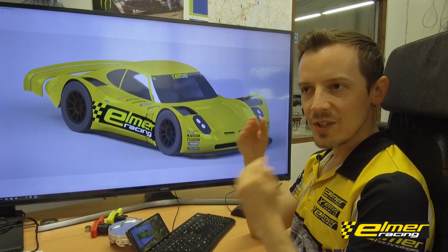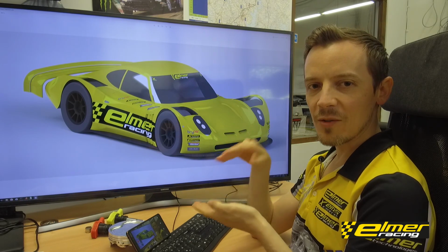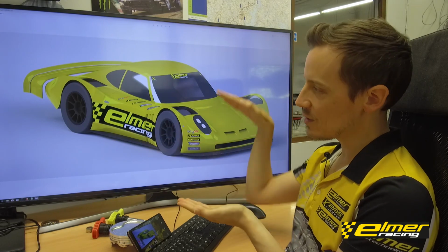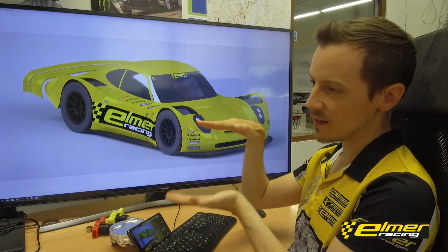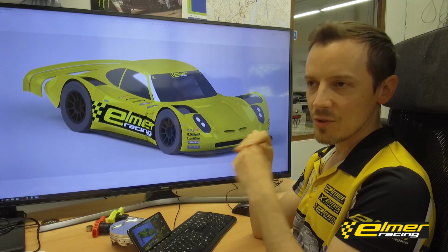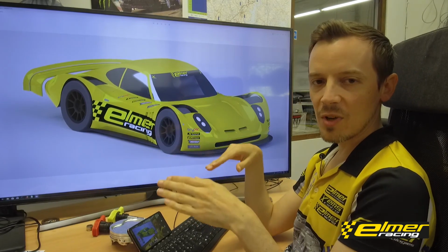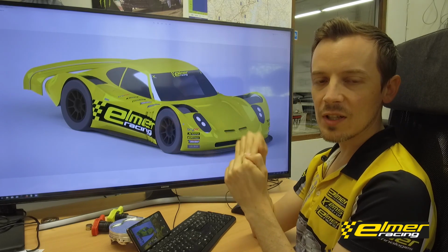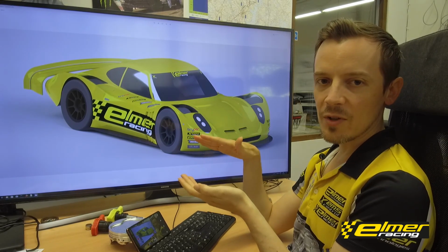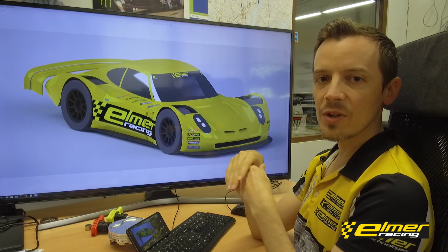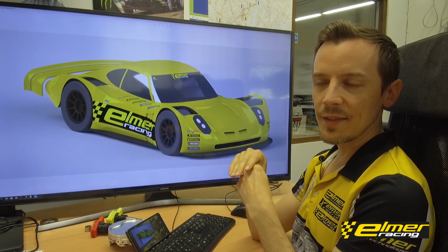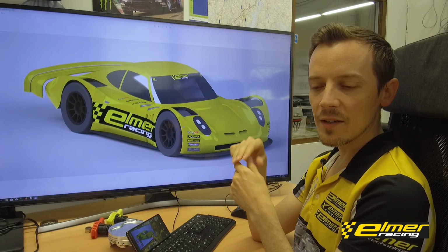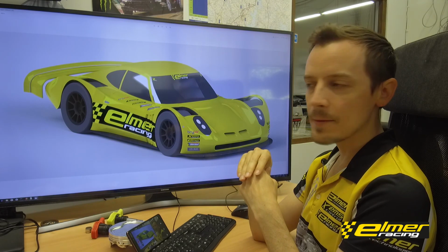So by definition, if you create downforce with gases, then that's only because you have a higher pressure on the top surface than the bottom surface. So of course you're reducing the pressure on the bottom surface as much as possible, but you're limited by the ambient pressure and how much of a percentage you can get down from there. And on the top surfaces you want to create as much pressure as possible, and on that you're limited by the flow velocity basically, and how high a pressure you can reach by that.